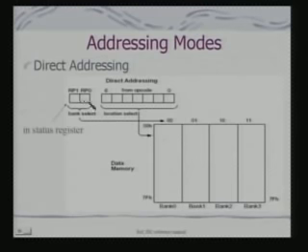So these 2 bits are used for selecting the bank, and the offset in the bank is specified by these bits which are part of the instruction. Therefore, in each of these banks, I can select a location by specifying this 7-bit address in the instruction itself.